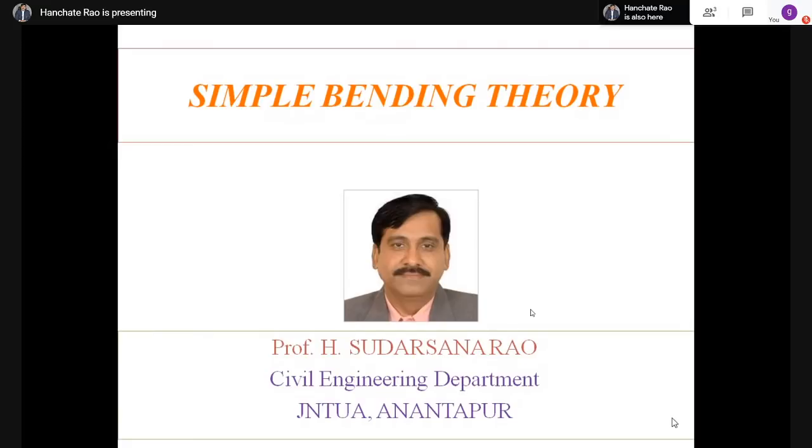I told you to remember the electrical wire. The sagging of electrical wires is an example of a sagging bending moment. On the other hand, a hogging bending moment is when, to the left of the section, the moment is anti-clockwise, and to the right of the section the moment is clockwise. Then it is called a hogging bending moment. It is a hogging moment. I hope it is clear.